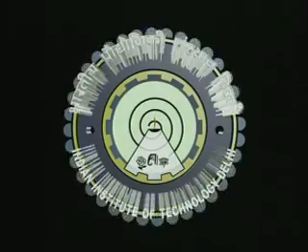Now, with regard to the polarity, polarity means whether high is the idle state or low is the idle state. So, using these two bits, these combinations can be identified. These combinations uniquely configure the clock signal for a slave device. So that's a facility that SPI provides.